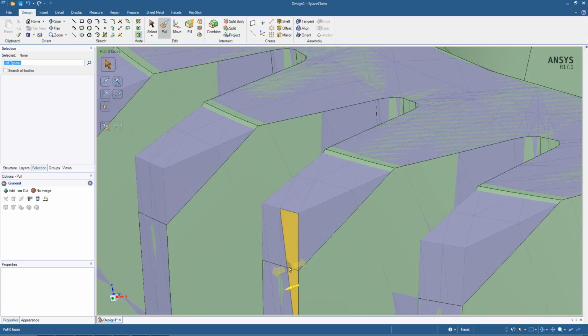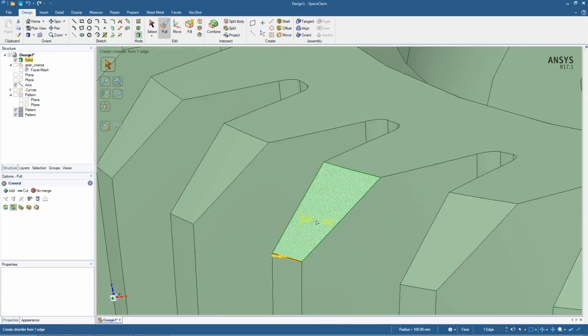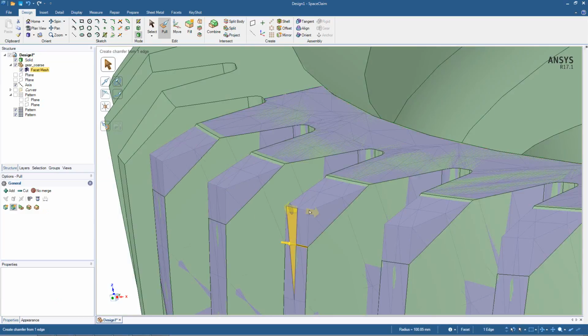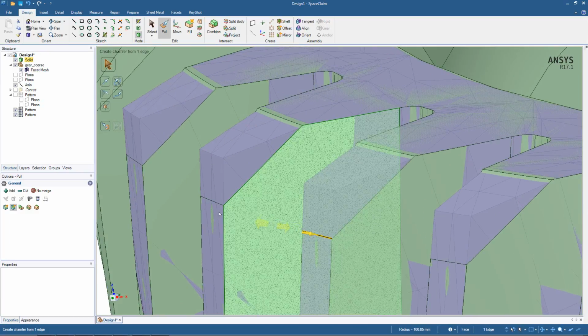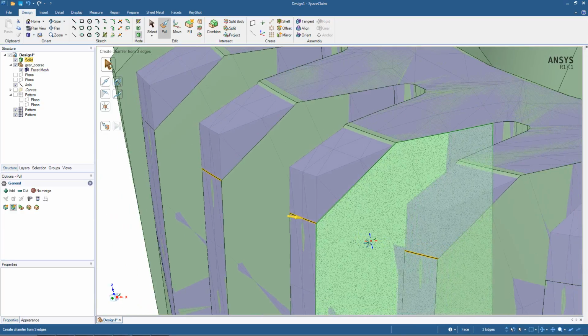It doesn't match up very well down on the bottom here. If I turn off the mesh, you can see that that's where this chamfer ends, but it should really go up to the top here. So we could do the same thing. We could grab all of these edges, do the same thing, meaning pull the edge to the size that we want this to be.